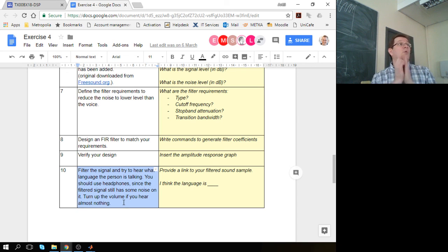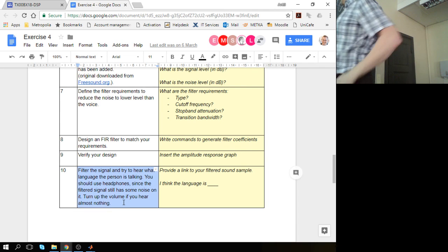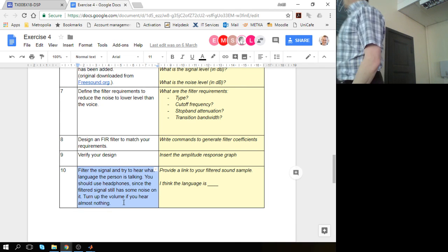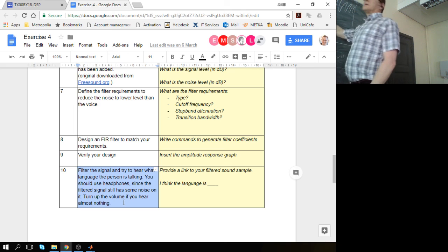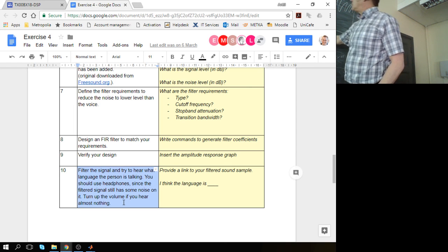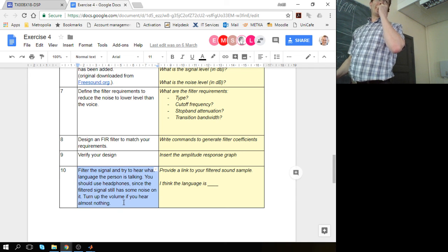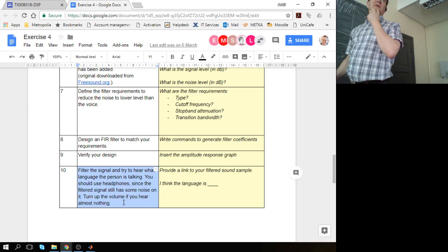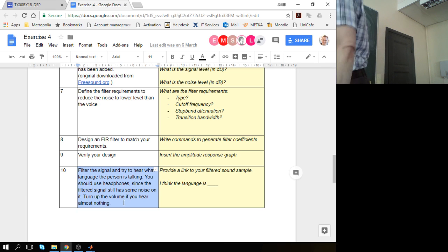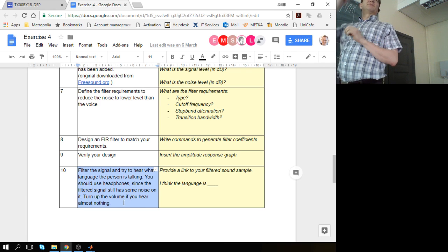One small hint: usually when you start the filter on a time-based signal, you might get some extra bang at the beginning of the filter. You can either apply a time-based window to get rid of that bang, or just leave it there, turn up the volume and let the amplifier saturate.